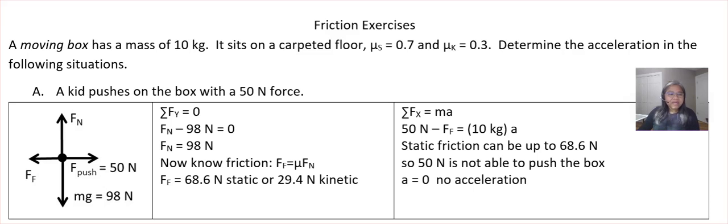The next step here is to apply Newton's second law of motion to each axis. We start with the vertical axis. The assumption here is there's no acceleration, or there is equilibrium vertically, so the sum of the forces along the y will equal 0. This will be our working equation. All forces upwards will be positive, and so that's the case for normal force, and all forces acting downwards will be negative, and that will be the case for weight.